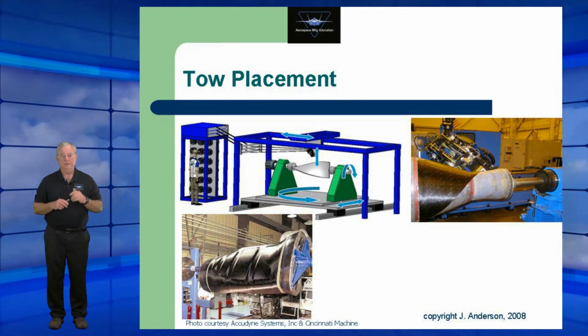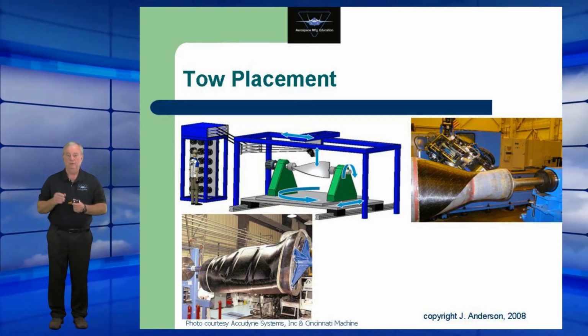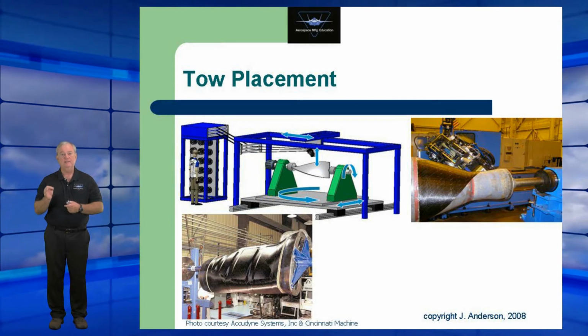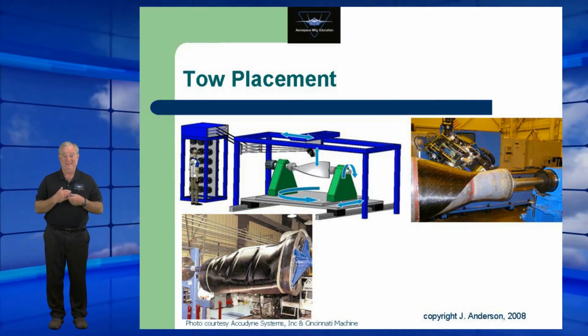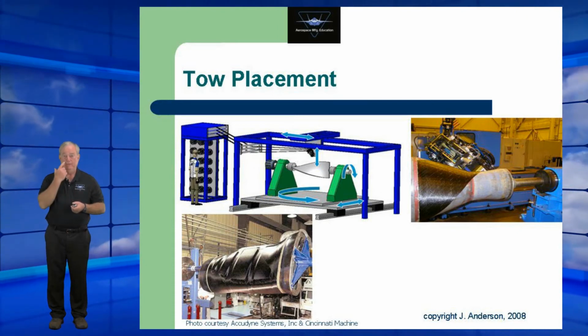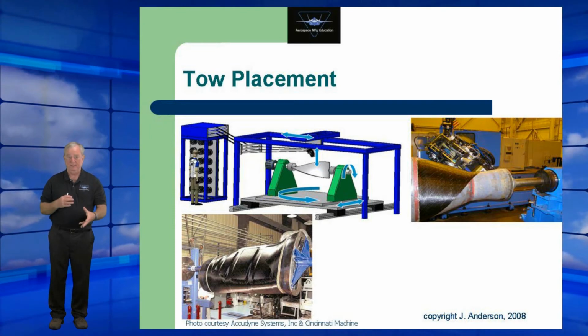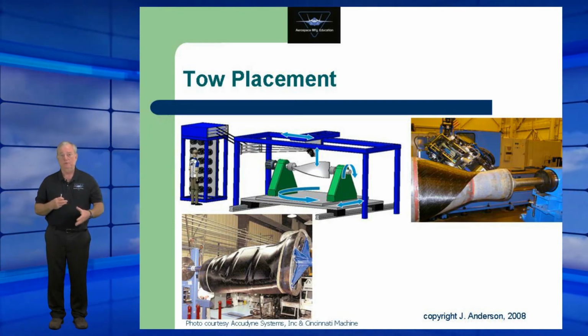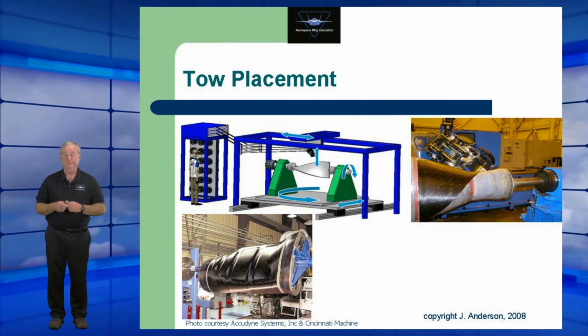Those rollers are actually a bath that puts a little bit of resin onto the fibers so that they're tacked into place. So once we wind up all the fibers, they stay where we put them, and then typically you do a vacuum resin infusion process where we bag this whole part and we pull resin in around the fibers or the fabric material.